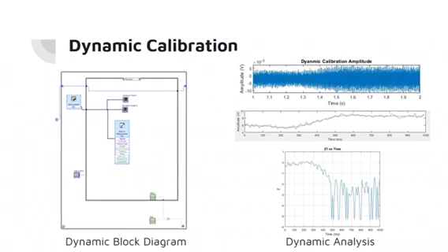Dynamic calibration. A tone of 698 Hz was played once again at a constant volume. The sound was moved from 60 centimeters to 0 centimeters quickly, while the DAC recorded the amplitude over time. This allowed us to approximate the response as a step response.